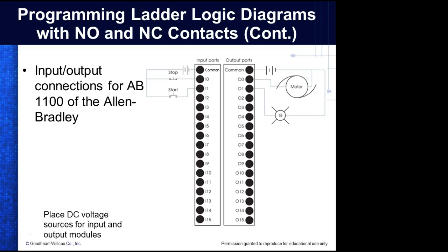If you look at an Allen Bradley modular PLC, it's still very similar to that guy right there. It's just that they use a more up-to-date PLC and a faster communication channel. This guy right here is 100 megabits, so this right here would respond instantly, right? The 485 is 19.2 kilobits, but you're the only one communicating over a smaller cable, so it's going to update instantly for you, right?